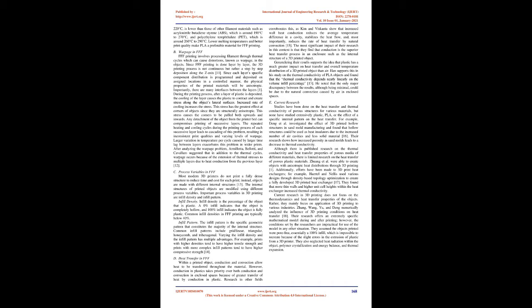PLA's melting temperature, around 180 degrees Celsius to 220 degrees Celsius, is lower than those of other filament materials such as acrylonitrile butadiene styrene, ABS, which is around 190 degrees Celsius to 270 degrees Celsius, and polyethylene terephthalate, PET, which is around 260 degrees Celsius to 290 degrees Celsius. Lower melting temperatures and better print quality make PLA a preferable material for FFF printing.